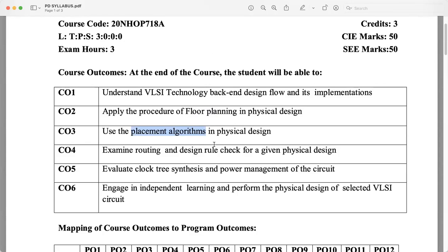That's because, as the wire length increases, the resistance and capacitance also increase. If they increase, our performance is going down, and we will not be able to have a better IC. We always look for performance, and if performance is not good, we will not like to have it, isn't it?